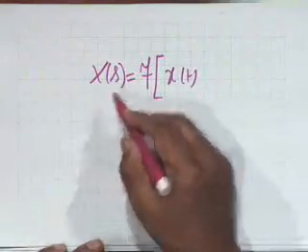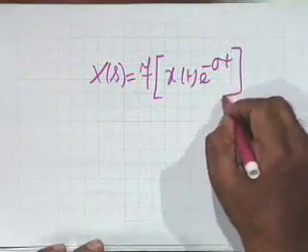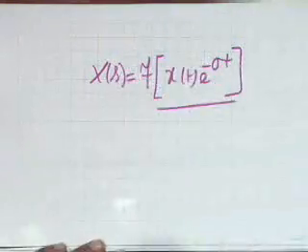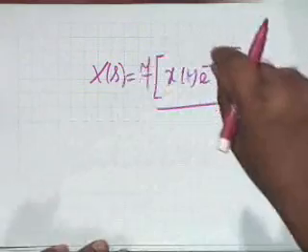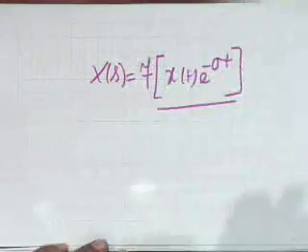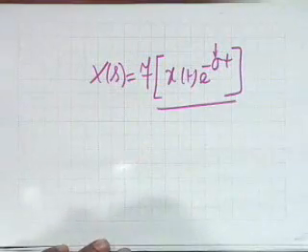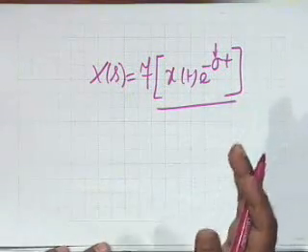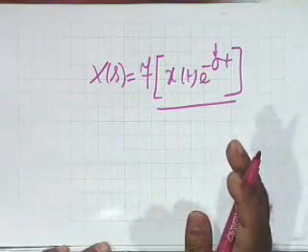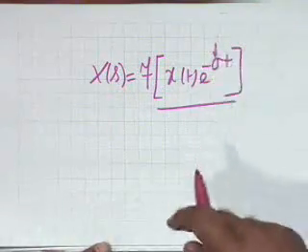What do you mean by the ROC? You know that X of s, very simple proof, we have already done this. X of s is the Fourier transform of x of t times e to the minus sigma t. Now, in this Fourier transform, j omega does not occur at all. That is, the vertical coordinate is not of any concern. It only depends on sigma, and therefore the ROC must be bounded by lines parallel to the j omega axis. Omega can take any value. It is only sigma on which the ROC depends, and therefore the ROC must be strips.